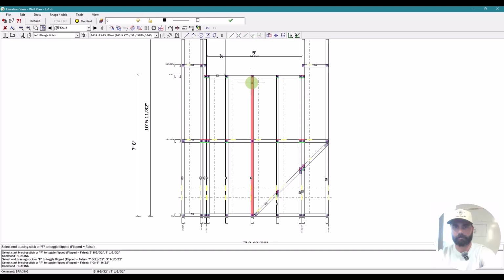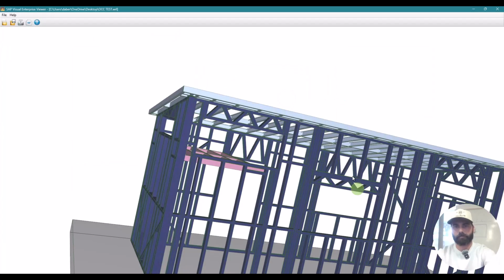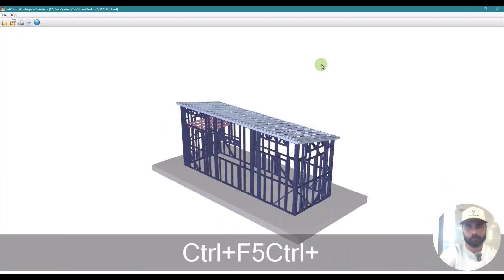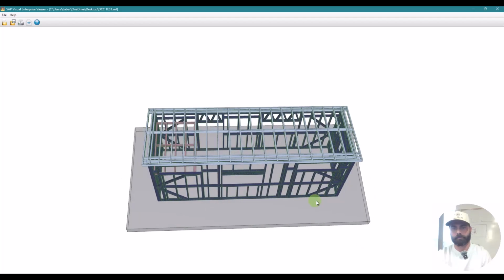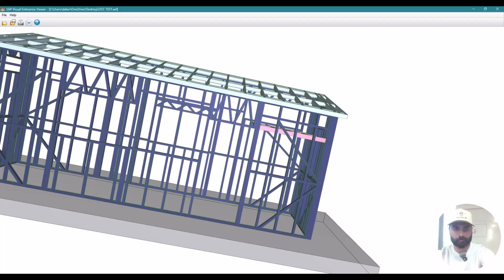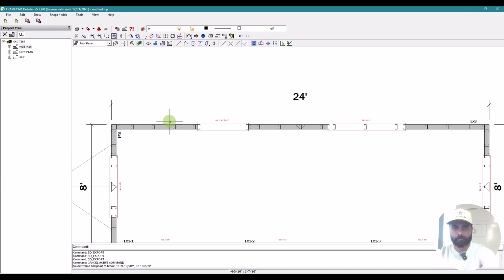I want 18, as close to 19, because we're trying to make it light. We want to make sure that it's structurally sound, but those are sort of working against you a little bit. So you just need consistency. Every time that steel comes off and you're measuring it to make sure that it's code compliant, you do all the things you can to make sure it's going to comply with your ESR or ICC certifications. So you're running that 1 foot stud on every project to make sure it's exactly 12 inches, and that's why you buy FrameCAD.